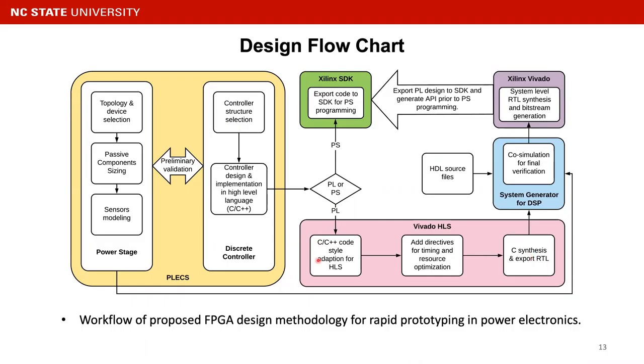The first step is adapting our code style for the HLS, and then we can add directives for timing and resource usage optimization. The final step is to run C synthesis and export our RTL design.